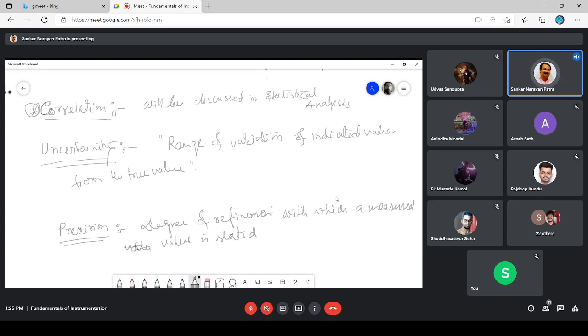Sometimes in the English language we say your answer should be precise. We sometimes use it to mean that your answer should be accurate, that you will hit the right answer. But precision means not only that it should have an accurate result, but that whatever you say, you will not change in future. So whatever reading your instrument shows might be less accurate, but it has great precision or repeatability: every time you do the same experiment, it gives you the same outcome.